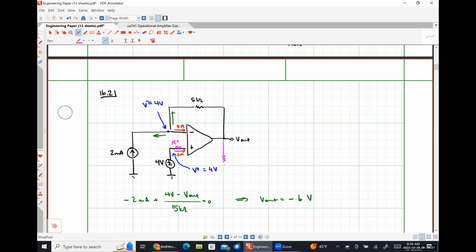What if I had included some load resistor, RL, across my output terminals? So I was trying to deliver power to some load, maybe a small speaker or something like that, using this amplifier circuit. Would the presence of this resistor RL in any way, shape, or form impact our circuit analysis? Absolutely not. Only if RL happened to have a value of 0 ohms, meaning that we were directly shorting our output to ground, would it have any bearing on our analysis whatsoever.